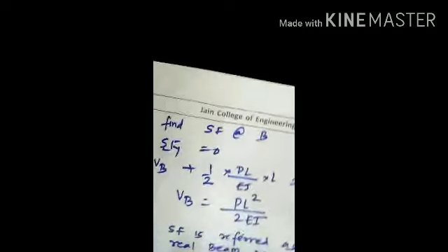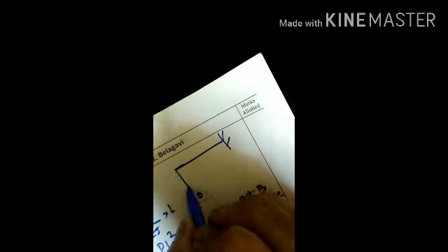And now how to do that? It is quite simple here. To find the shear force at B, take summation Fy equal to 0. I shall draw the diagram here again for better understanding. So the M by EI diagram with the conjugate beam was drawn like this, wherein the value of PL by EI has been considered here, and point B is considered here.